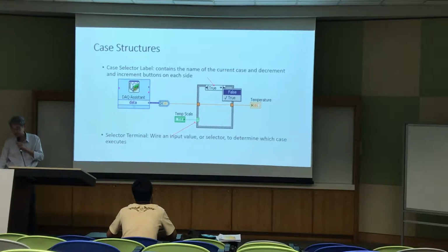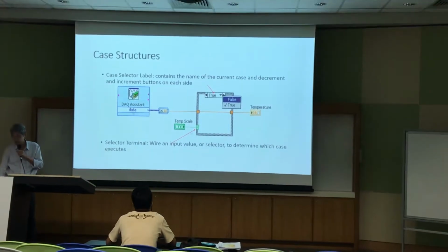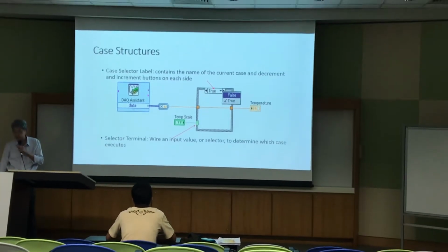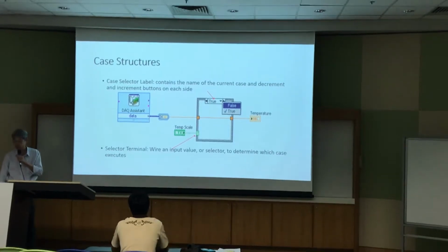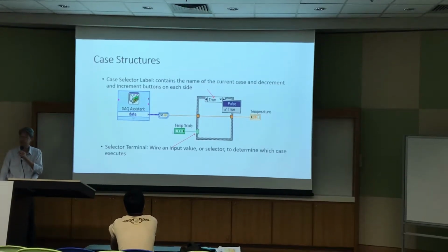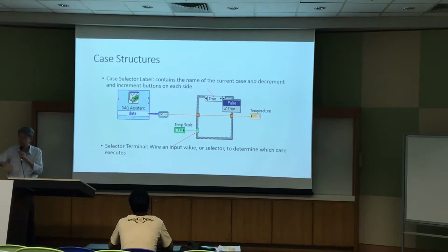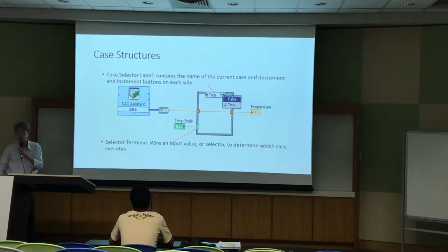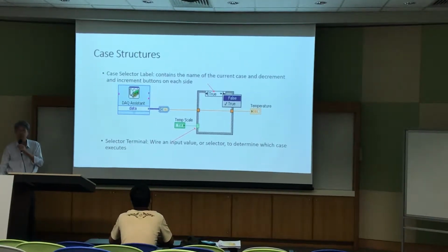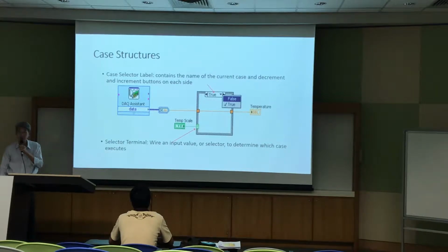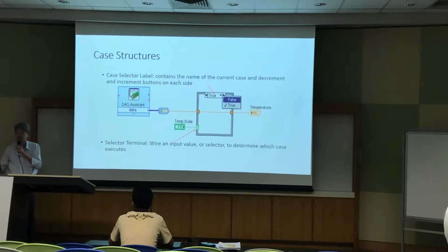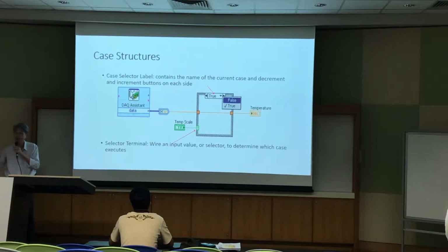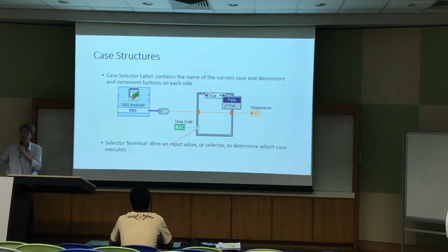Okay, so this state case selector, it can take in Boolean, true or false, only 2 cases. It can take in enum, many of them, up to you how many enums you want to key in items. You can take in numbers. However, numbers, there's a restriction, only whole numbers. In other words, integers, no floating point.